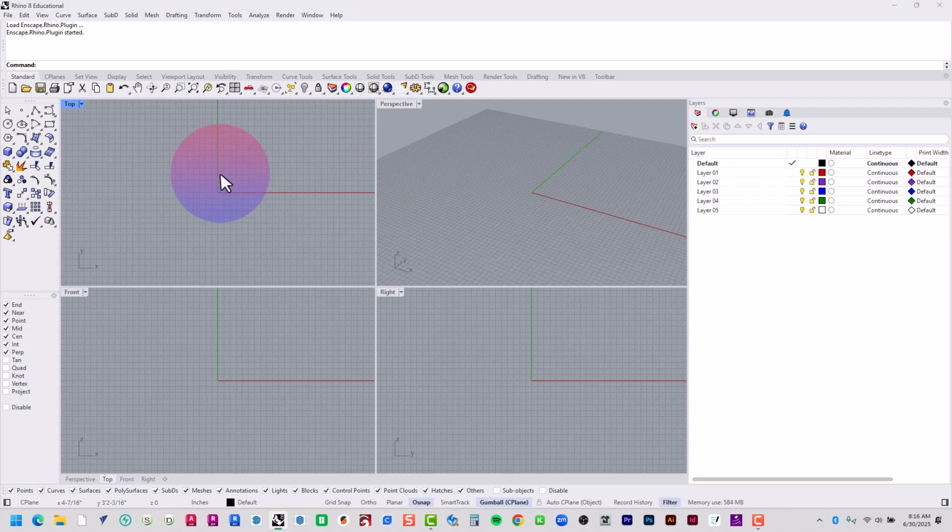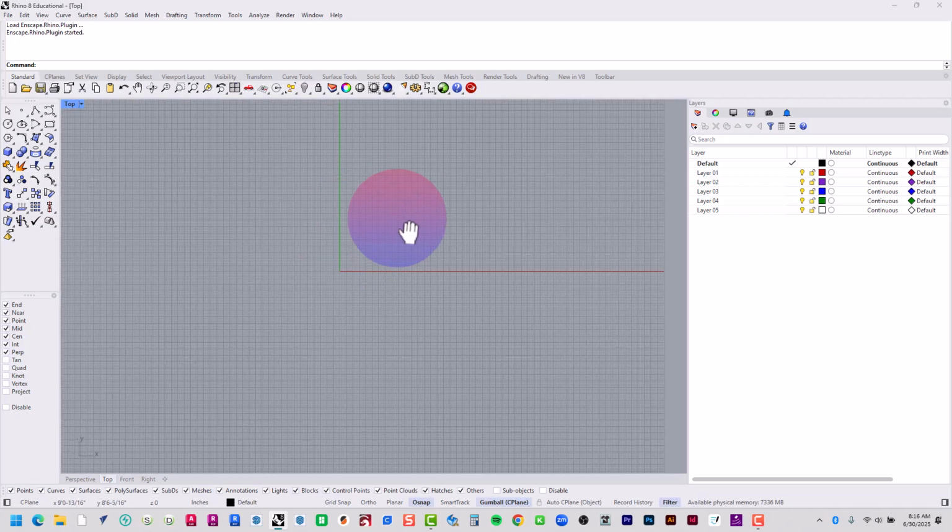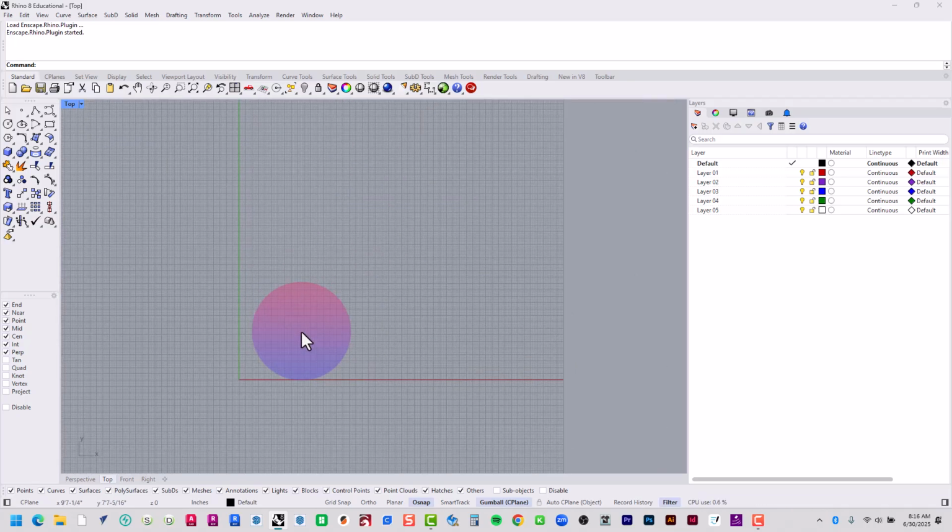All right. So today you guys are going to take your measurements and bring them into Rhino and create a floor plan. We're going to do a 2D floor plan, just two-dimensional first. And then maybe later on we'll consider creating a 3D model of it, but really the goal will be to create a two-dimensional floor plan. We can print it out to scale on 17 by 11, and then we can have that as reference so when we start to design our cash wrap, we have that for reference.